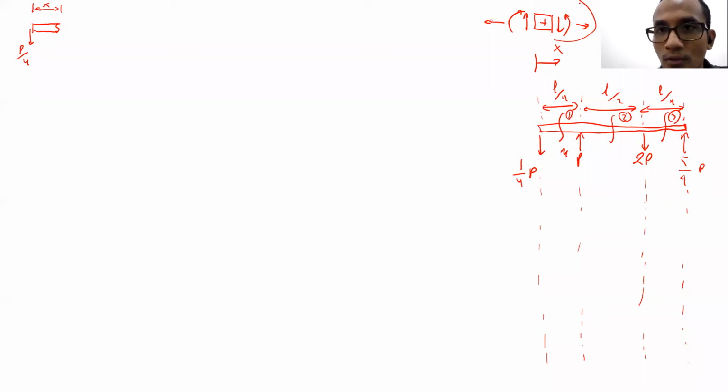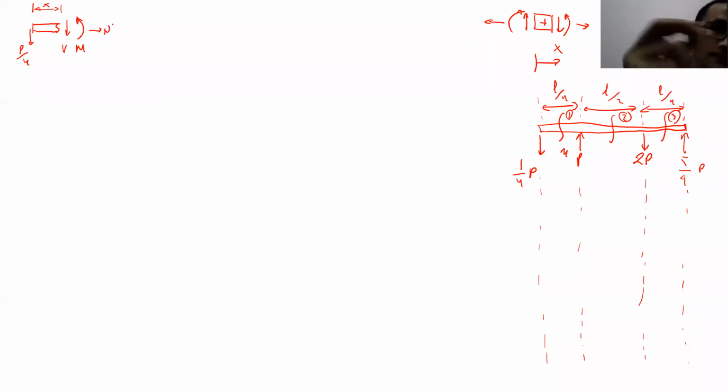We have to follow the standard. That's the easiest way to do it. So the shear is going down, and there's a tension force to the right. And what else? A moment. Counterclockwise or clockwise? Counterclockwise, correct. Counterclockwise moment.